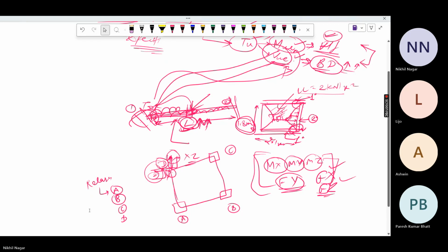Okay. So these are very much special cases. I think you will not see them in your live project, because we don't prefer them. You can imagine that if the load is coming on this slab, your yield line, meaning your failure line, will be passing through the diagonal of this column, the diagonal of this plate.